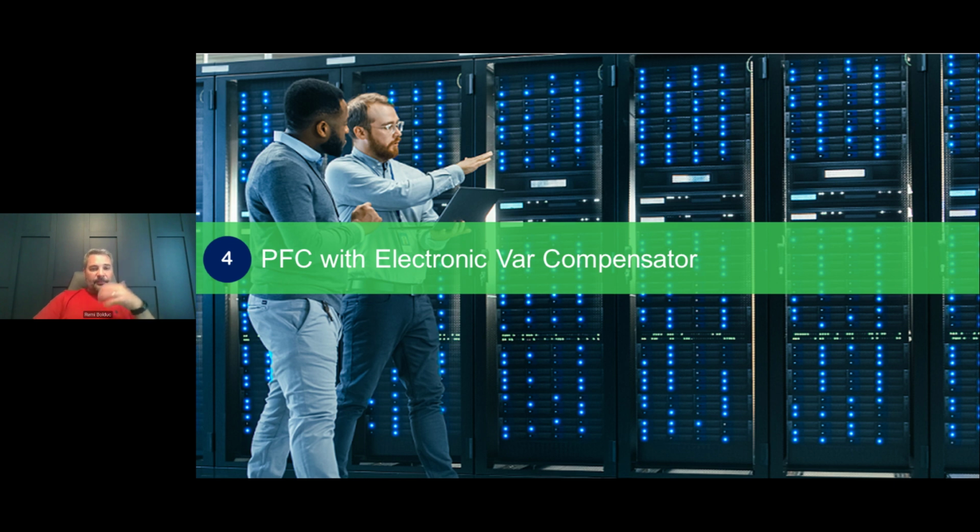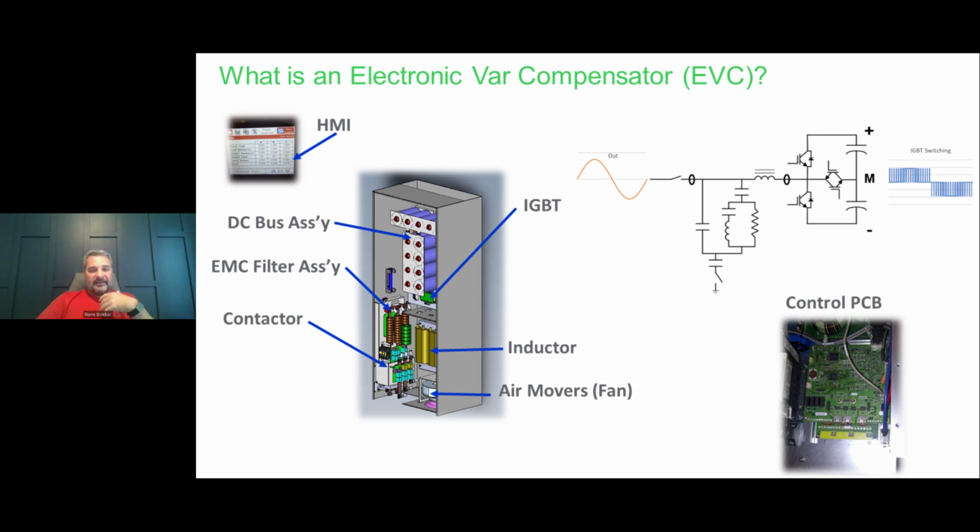And next, it's a little bit about the future, what's coming down the pipe from various manufacturers. What we've seen is that active harmonic filters have evolved. They can obviously mitigate harmonics. They can also correct power factor in real time and do load balancing. So the idea of manufacturers is actually to bring this idea to low voltage compensation.